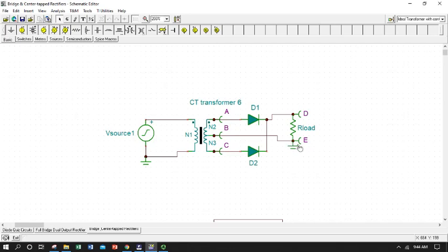By grounding our load, or by grounding the center tap and having a grounded primary, we just lost our isolation. Unfortunately, because ground is ground, if there were any stray currents, they could communicate through the earth ground. Just as a note, these grounds don't both have to be there, because this is an isolated transformer. If we didn't want anything on this side of the circuit talking to the primary, we would take away one of the grounds. But we don't need to for this simulation, so we're going to leave them there because it makes it easier to look at our reference voltages.